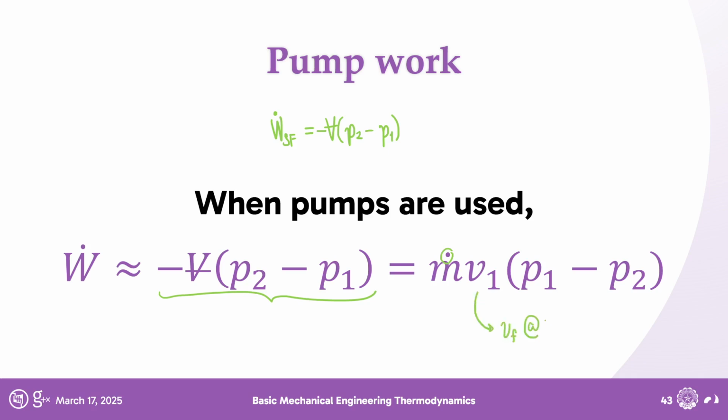at your first temperature, but usually you will also see in problems that the temperature of water as it's being pumped does not change. So it doesn't matter if you take V1 or V2 as long as the temperature stays the same. But just for uniformity, let's all just take the specific volume at state 1.